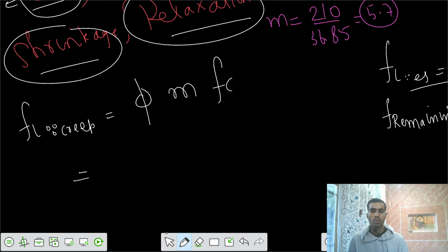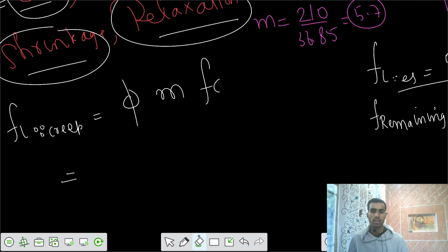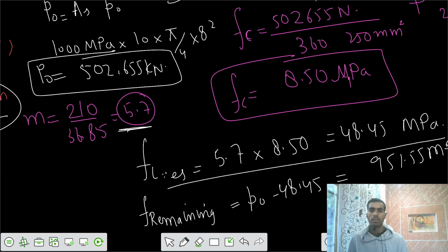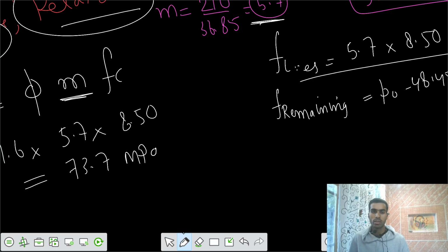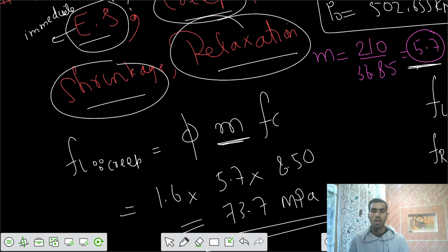Phi value has been given to you, 1.6. m value 5.7. fc 8.50. What is the total value we have now? Is that 73.7? 73.7 megapascals. This is the loss because of the creep.